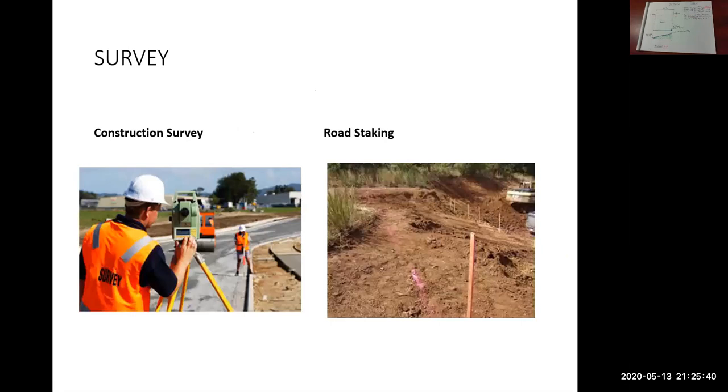So a couple more survey photos. There's the surveyor with the total station. There's the rod person, rod man I was going to say, but rod person. Looks like they're shooting the gutter line of this curb. So maybe they're as-builting the curb.